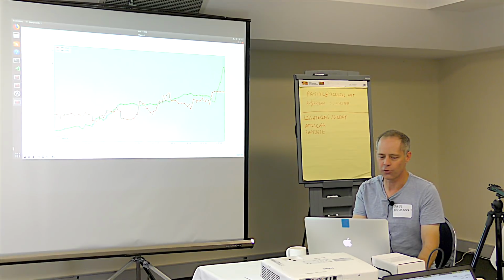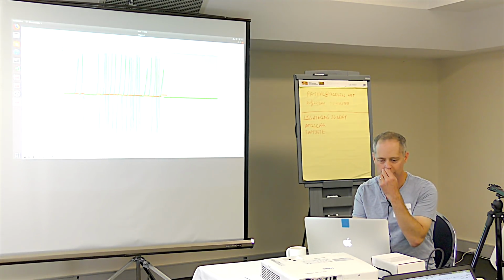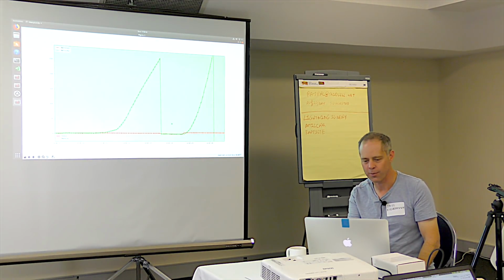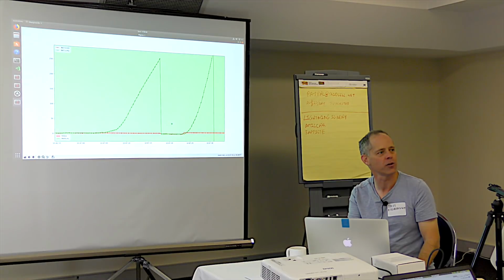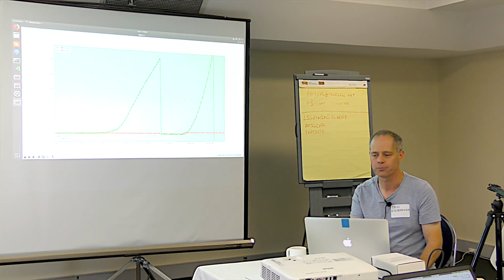So I just thought I'd throw that log in there. We won't do too much more on this log other than the vibration. And the other characteristic you'll see is that after it's been climbing ballistically for about 10 seconds, it then does a reset. And then the process keeps on continuing. So you end up with these series of climbs. And unless somebody's able to fly in a non-height controlled mode, it usually results in loss of vehicle.